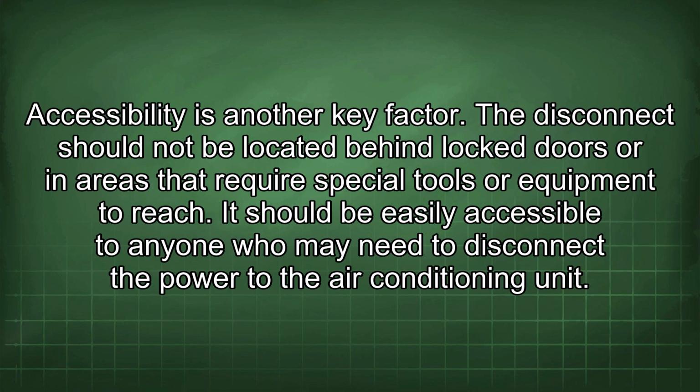Accessibility is another key factor. The disconnect should not be located behind locked doors or in areas that require special tools or equipment to reach. It should be easily accessible to anyone who may need to disconnect the power to the air conditioning unit.